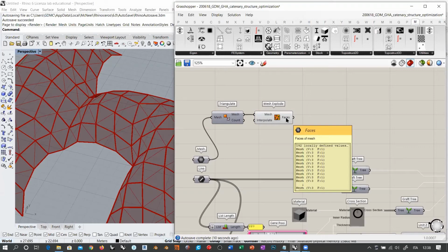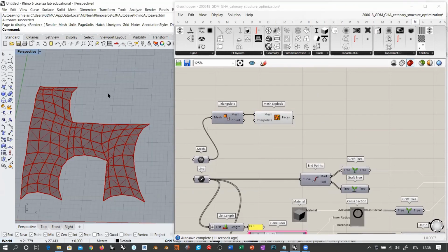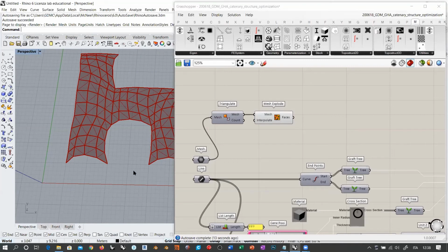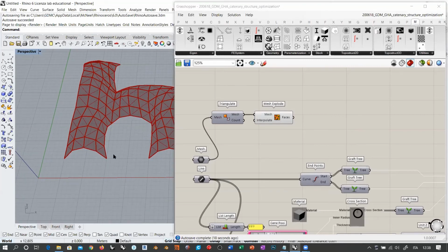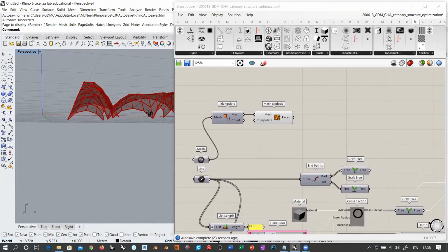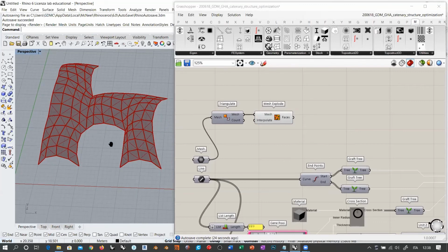So you see that we have 192 meshes, each one having 3 vertices and 1 face. So they are triangles. And you can take them and eventually also lay them flat on the ground plane, on the XY plane, in order to prepare them for some cutting technology like water jet cutting or whatever. Okay, so this is the easiest thing.